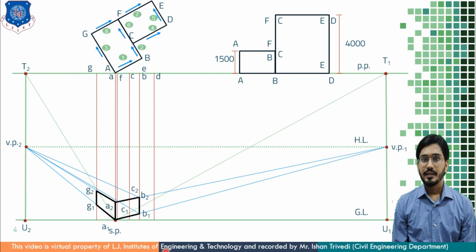But is that B point also resting on the picture plane? No. B point is not resting on the picture plane. So from B, which is the nearest point that is placed at the picture plane? Then from B, I have to come up to point A. And the A point is the only point where I can measure true height. So for getting the actual C point height, I have to measure height at A only.